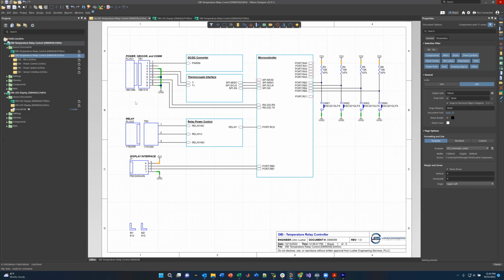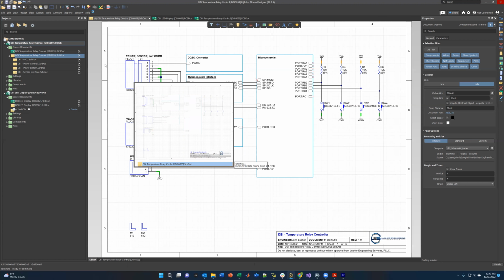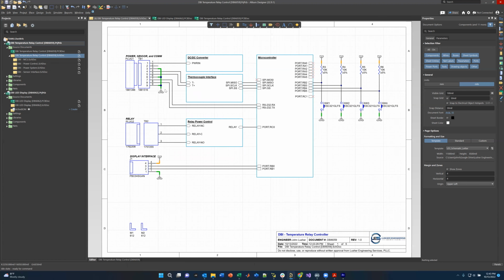You actually buy these. I will show this to you in a little bit in the 3D view of the board, but this is a terminal block that has a plug, so you can hook wires in to the left-hand side of this plug. You hook up the wires, push the plug into the receptacle, which is the terminal block, and it plugs into the board. This plug is removable from the terminal block, so an electrician would wire their wiring to this, and that would then plug into the terminal block, which is what is on the board.